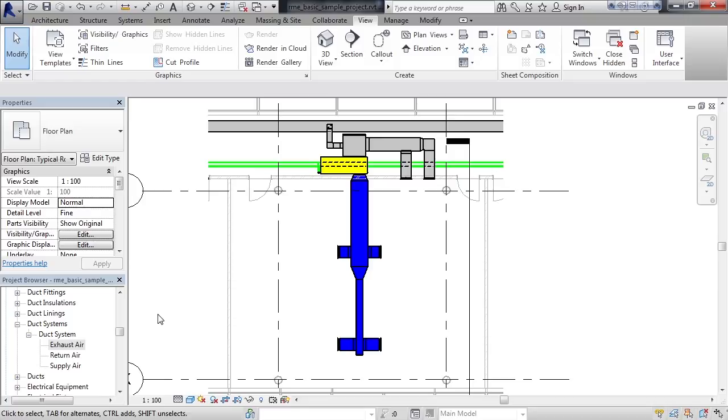In this lesson, we'll cover checking systems. For all the systems that you can create inside of Revit, HVAC system, plumbing system, or electrical system, you have a variety of analytical tools that you can use to inspect your systems. For example, the system on our screen right now is a duct system, HVAC system, if you will, for supplying air, hot and cold to your building.